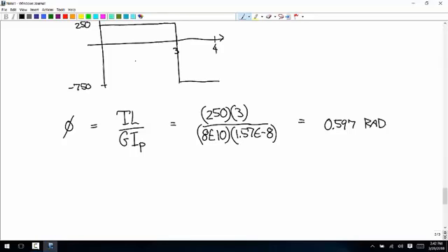But what that says is it goes through an angle of like 35 degrees or something. 34.2. Yeah. 34.2 degrees is the angle of twist right where that external load is applied. And then it goes back to an angle of twist of 0 at the 2 attachment points.